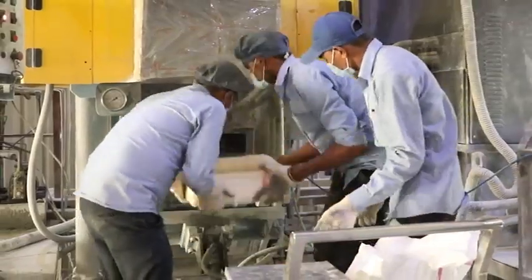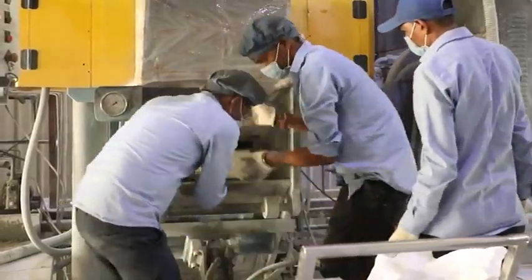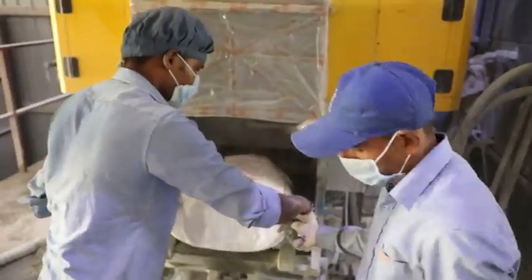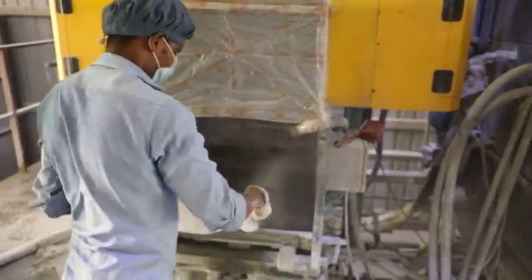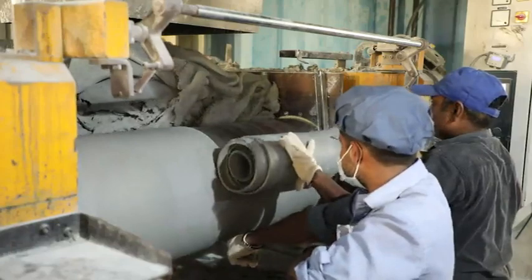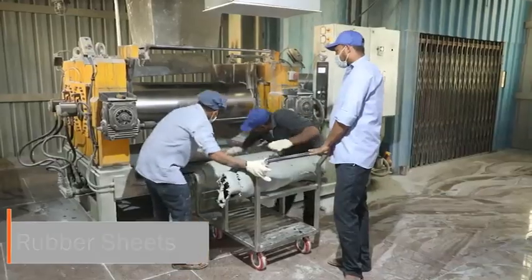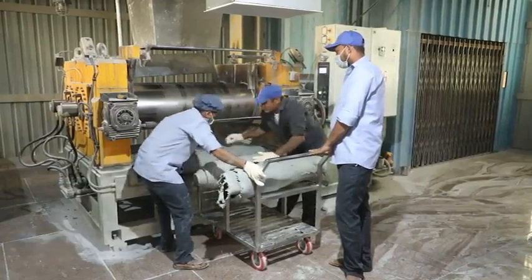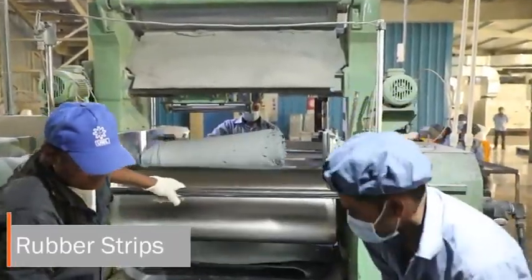For the purpose of kneading and intermixing, firstly dispensed rubber is added to the mixer, and then fillers and fine chemicals are added in the mixer. The material is mixed thoroughly for homogenization. The homogenized material is then shifted to a mixing mill for conversion to rubber sheets. These rubber sheets are again transferred to the mill for making rubber strips.